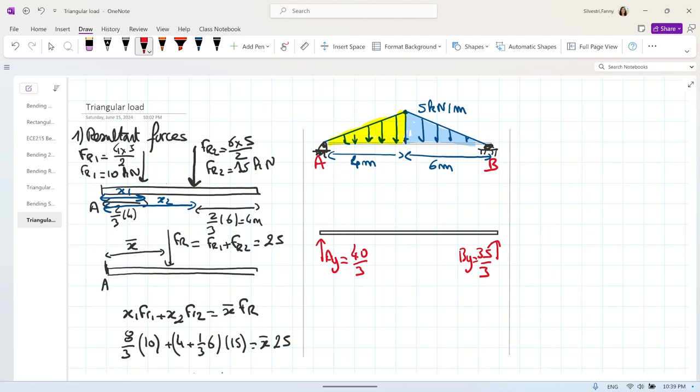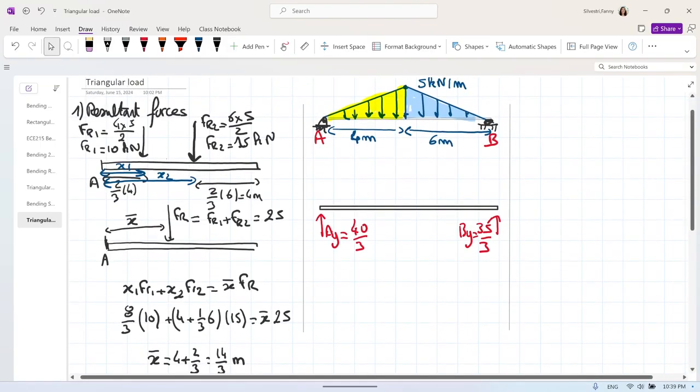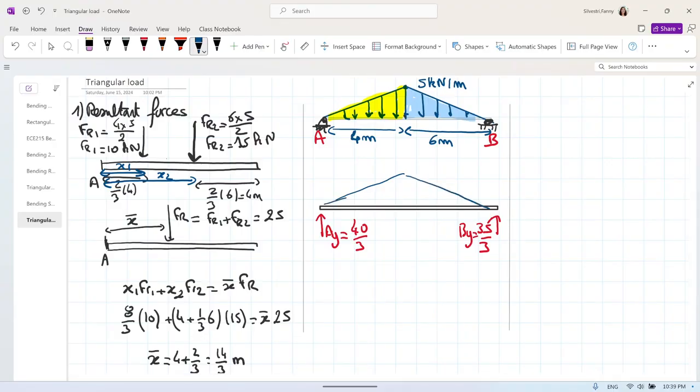Okay. So for the drawing of the shearing force and the bending diagram, we need to come back to the beginning. We need to come back with that distributed load. We can keep this drawing of the distributed load on top of that, because of course a distributed load and the punctual force do not create the same internal effect inside the beam at every point.